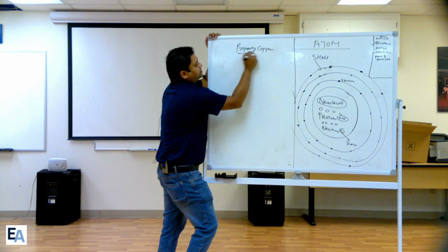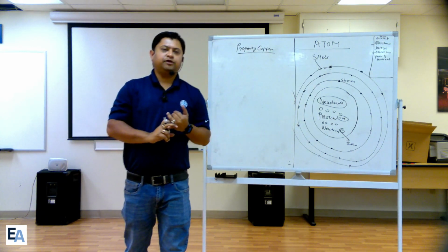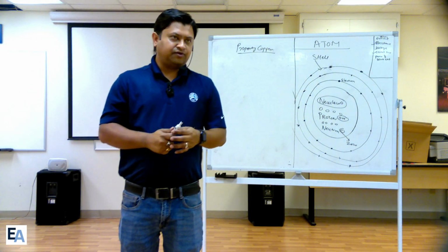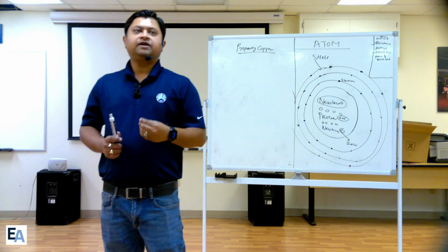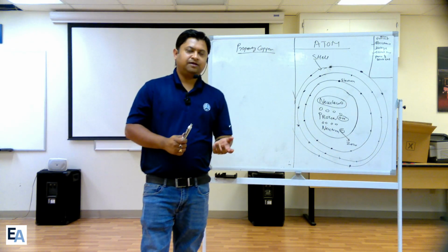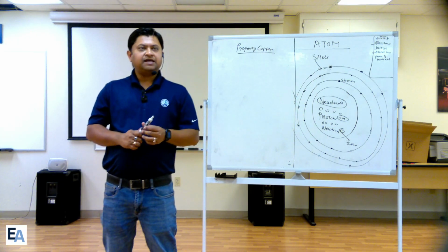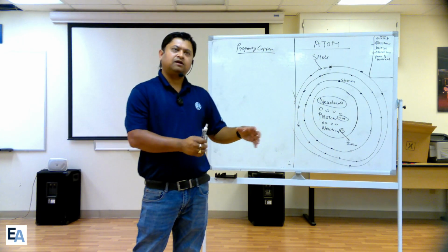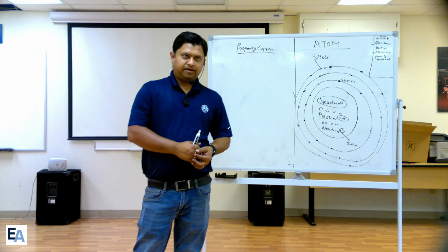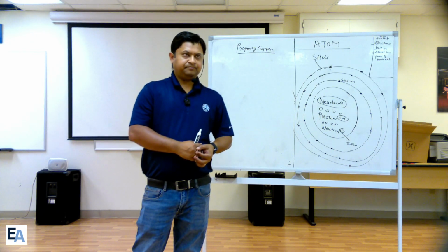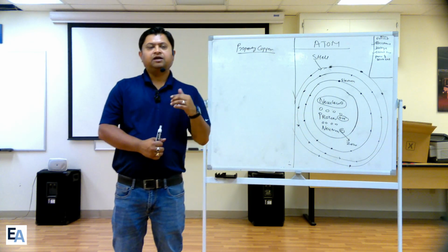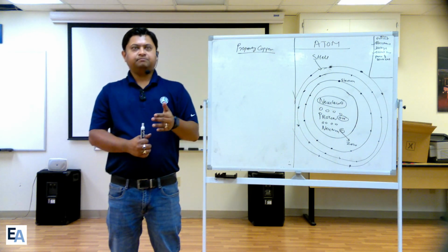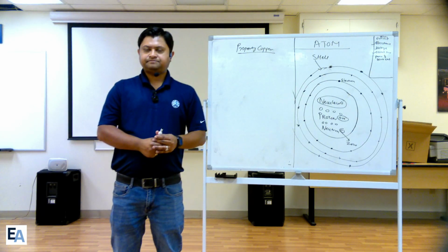Simple mathematics. Copper is the material which we are using for electricity. I told you we are not using silver because it is very costly, right? We can build the transformer with copper, we can build the transformer with aluminum as well, okay? So why we are not using aluminum in this case is, aluminum has some limitations. In very small transformers, people use aluminum, because they don't have to carry much current. Aluminum is not a very good conductor compared to copper, but it is still a very good conductor.